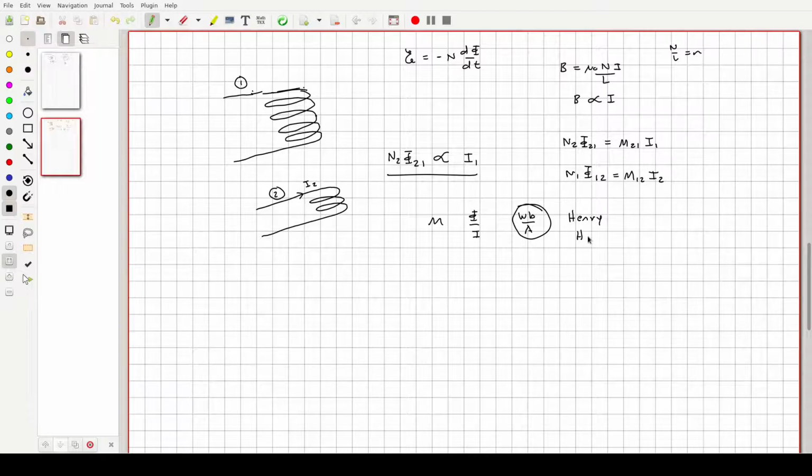Okay. So, much like capacitors, you see capacitance on the order of 10 to the minus fifth, 10 to the minus sixth farads. Here, with a coil, you see inductance, which is the property of a coil, we say. It's on the order of 10 to the minus fifth, 10 to the minus fourth, 10 to the minus sixth henries. Okay, so again, what you're really looking at is the effect of one circuit on another circuit, and it's this type of effect right here.